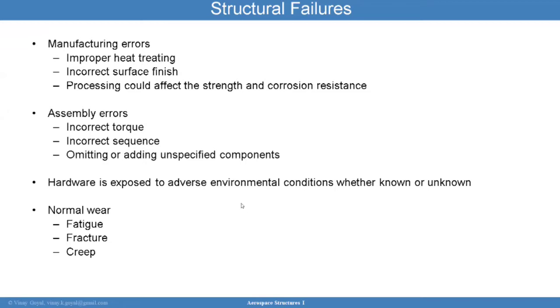Hardware can also be exposed to adverse environmental conditions, whether known or unknown. And I'll go through some of those examples, but salt environments can cause corrosion as an example, and that's an environmental condition that can be a problem. I'll go through that in a little bit more detail as we move forward. You also have normal wear, such as fatigue, fracture, and creep, and these are areas that occur when a structure is in service for a long period of time, and those need to also be considered in the design process.